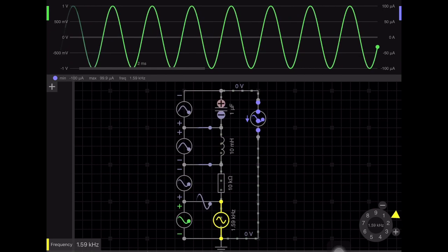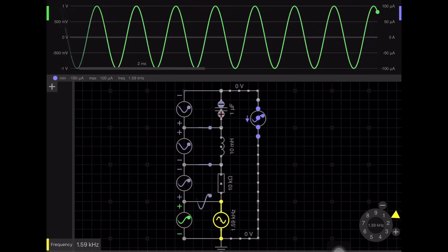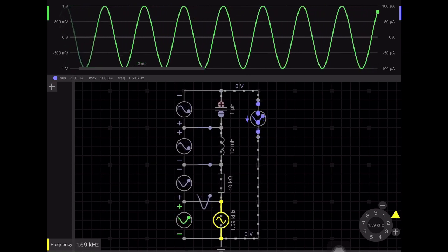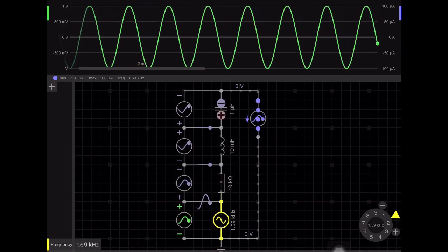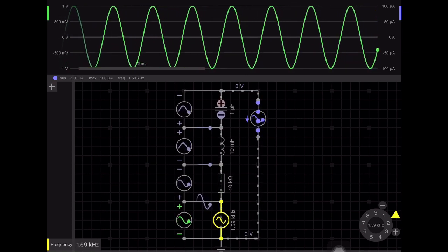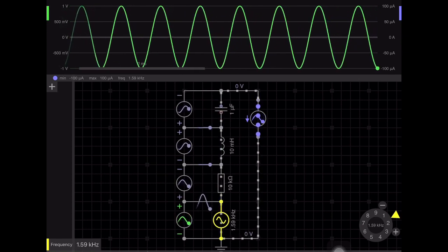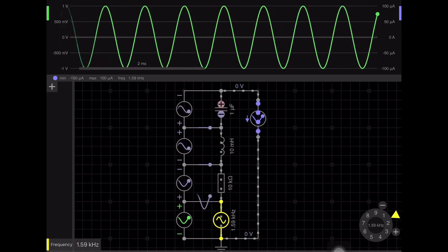During this condition, there will be maximum current flowing through the circuit because there is no opposition due to impedance. When there is no opposition due to impedance, the entire circuit now is resistive, and that's why the voltage and current are in phase now.